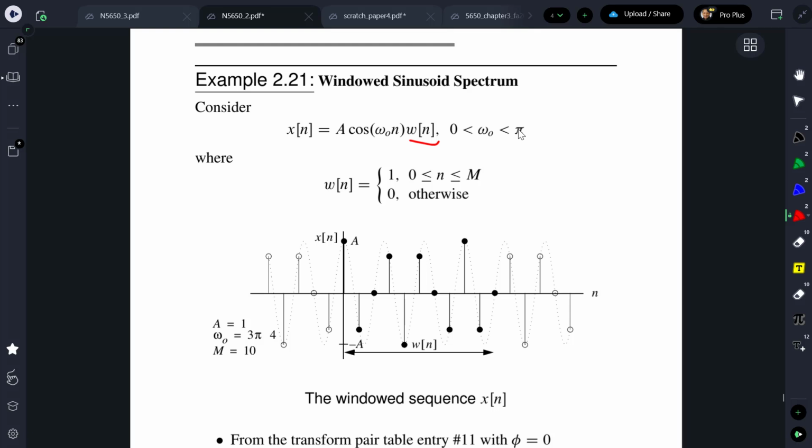So you can think about it if it was a data acquisition system and you were streaming some data at yourself from a sensor. In this case, it's a very simple sinusoidal signal, but it could be all kinds of different waveforms. But you're going to gate it on and gate it off, or you're just going to capture a buffer. Maybe you've played with software-defined radios, where you build a capture, like if you do it in Python or any language for that matter. GNU Radio Companion also lets you do this too. You just capture so many seconds or milliseconds or whatever. So you have a record of data, and now we're going to do something with it.